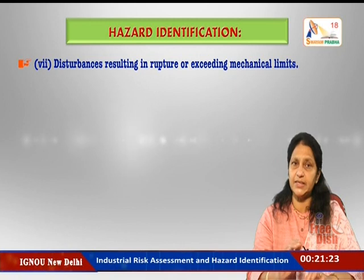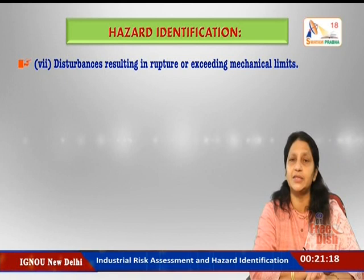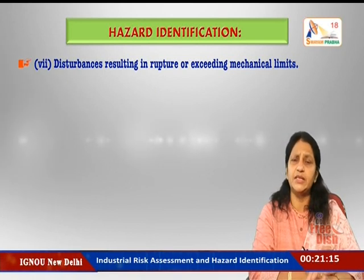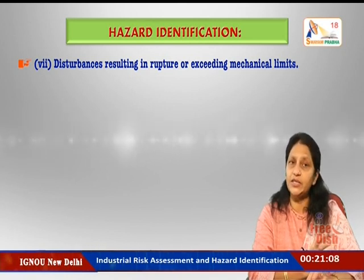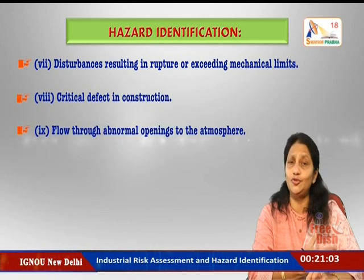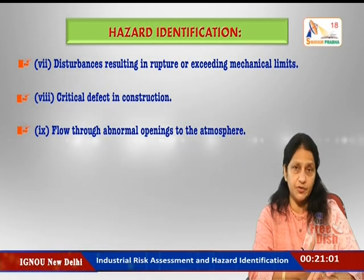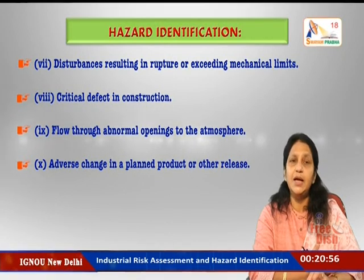So the assessment starts with the examination of the dangerous disturbances of that particular industrial plant. Maybe sometimes there are disturbances which result in the rupture or sudden exceeding of mechanical limits. So that time is also most important. And also critical defects in construction, and then flow through abnormal openings to the atmosphere, and adverse change in a planned product or other releases, and the disturbances should be further developed until the immediate causes can be identified. For example, human errors.